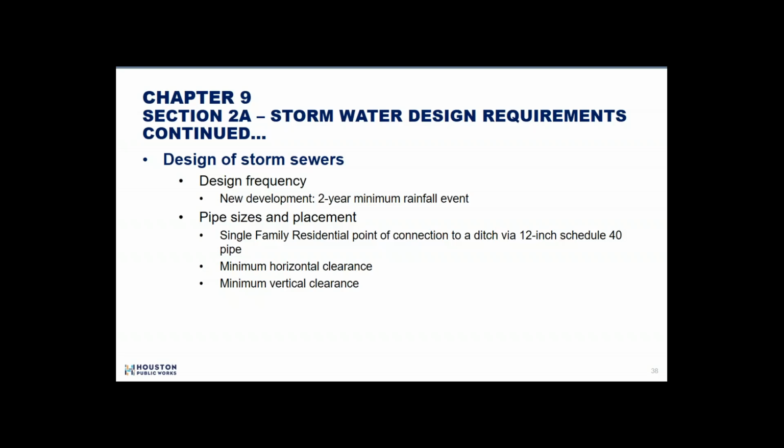Especially on in-house projects, we're going to have to maintain 1.5 feet. If you're doing retro work, which a lot of developers have to do, we're just going to work with you as best we can to deal with this 1.5 foot clearance issue. So bear with us on that. Do not assume you get 6 inches if you trench it. You need to do your designs to adhere to the 1.5 foot clearance.